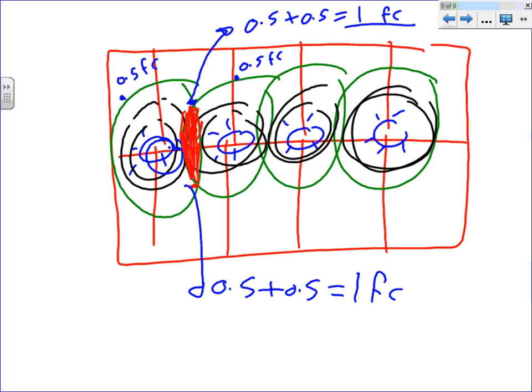The reason, Spencer, why they overlap it is because what's the worst scenario that I want to avoid? The area right in the middle is the furthest from both of these fixtures. If I don't overlap them, it's going to be dark. So they overlap them slightly, so that the furthest point from the two fixtures gets a little bit more light from each one of them. It adds up to an even light. The same thing, guys, over here. The overlap area is going to be added up between the two fixtures.